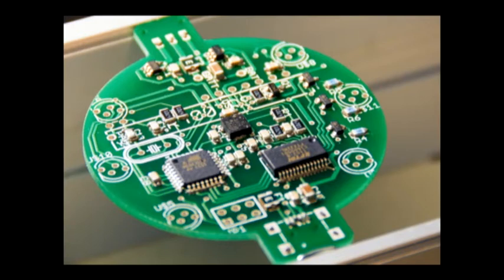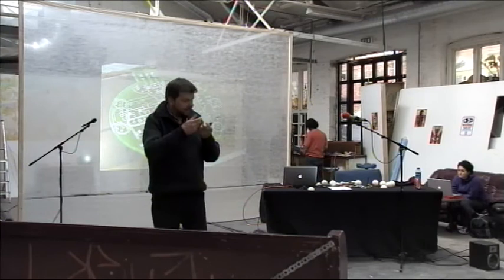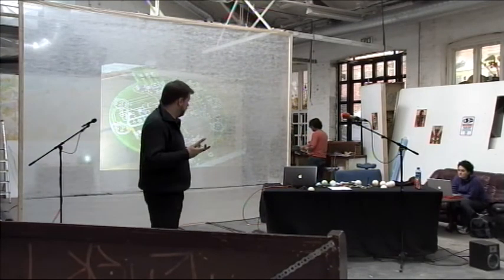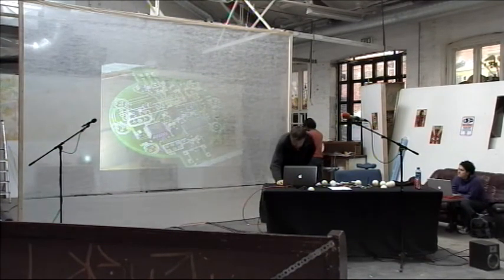So we have a little injector thing and a little needle. It's filled with some kind of malleable solder stuff. And then manually we place this solder paste on each single pad, place all the components, and we bake it in an oven for like 2 minutes, and then all the solder paste melts, and the components are soldered to the circuit board. So it's soft, and when it goes to the oven, it gets harder. Yes, exactly.